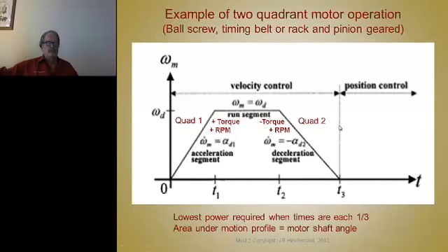Now, if I could accelerate in zero time and get to a lower speed and stop in zero time, the area underneath that rectangular move would be equal to the same area as this. So you could go through that angle in those extremes. You come up in zero time, hit a lower speed, and stop in zero time. Or you can take the maximum acceleration time and do a triangular move. But the area of the triangle, the area of the rectangle, and the area of the trapezoid, they all have to be equal.